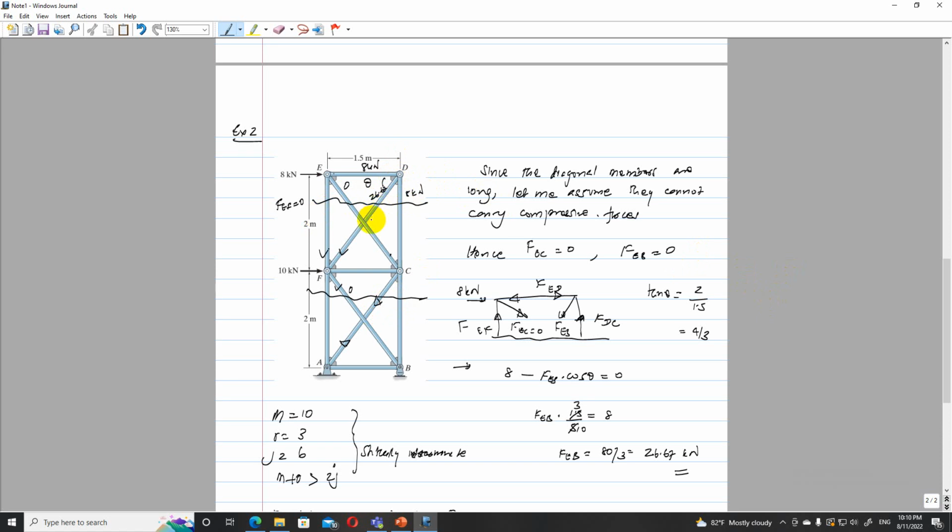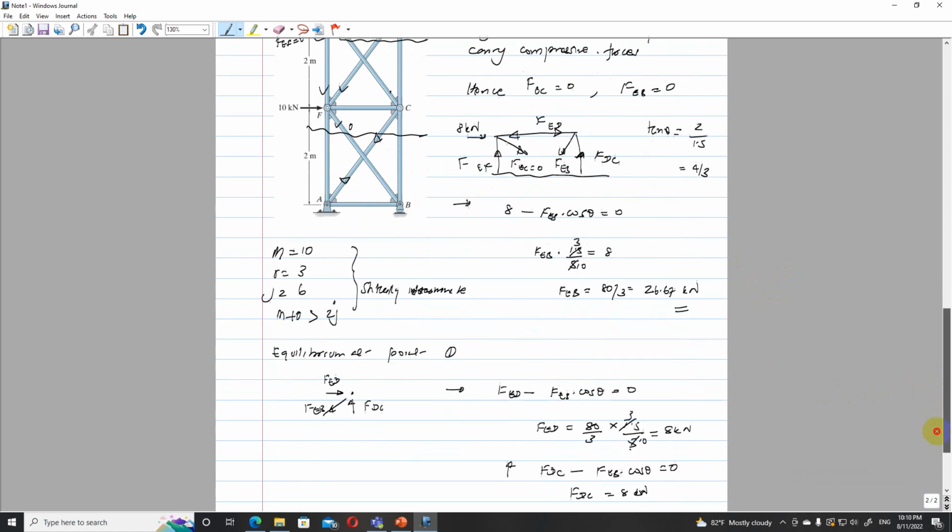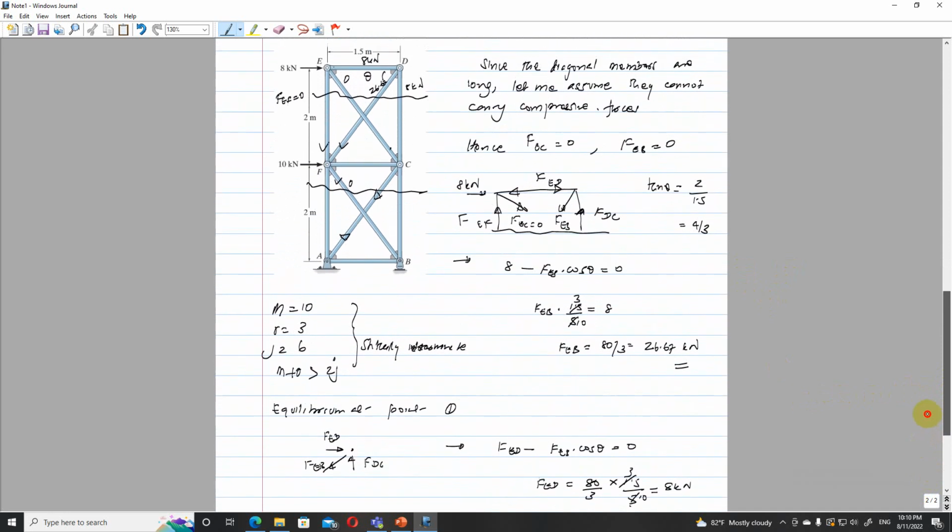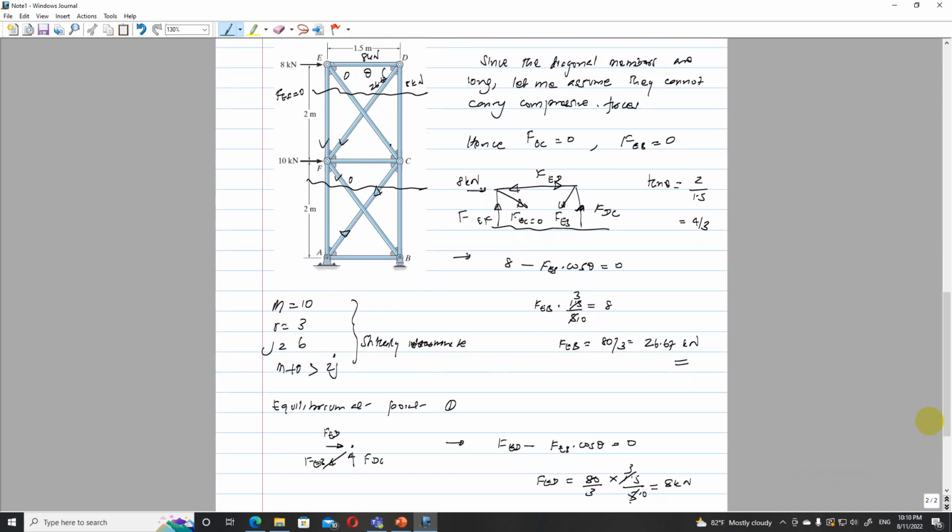So now I need to get a cut and find the other diagonal. So the method I am adopting is the first one, that is diagonal under compression is equal to 0. So I am considering a tensile force diagonal only. So if you apply a lateral force here, this member tends to move towards positive x direction and D will tend to move towards positive x direction. So eventually these members will try to pull it and then they will experience tension.